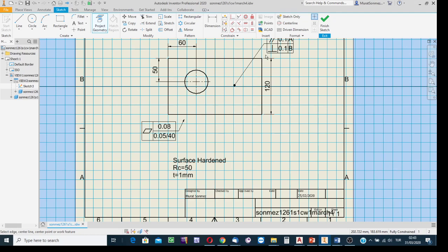Well, in applying the windowing method in AutoCAD, bring the cursor to the corner of the region where you have something to select. Click the mouse, release the button, and move the cursor.